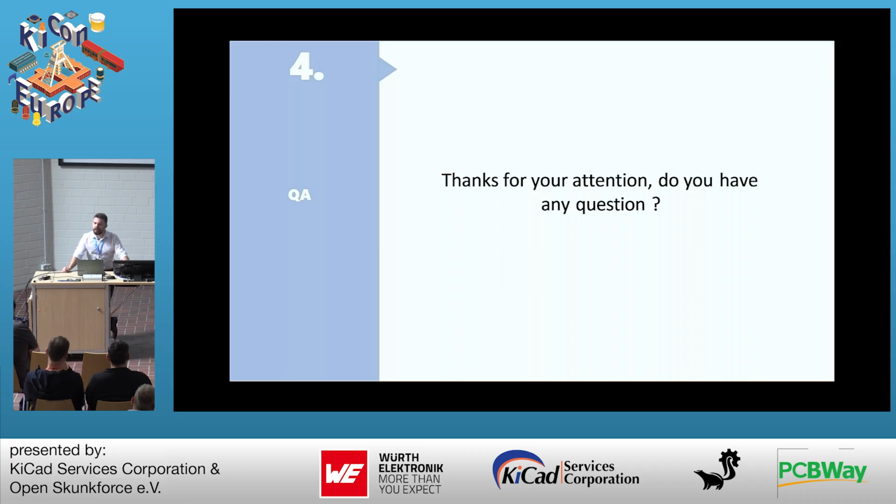And then we will automatically ask you if you agree that we also fill the vias with resin, but you have to know that it will create some additional charges. If you don't want us to put some resin inside it, there is the issue that applying the solder paste can create. Then your second question was about side plating. No, it's not possible.